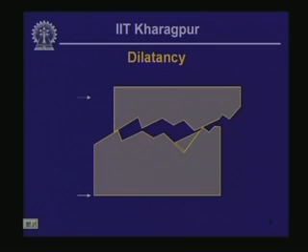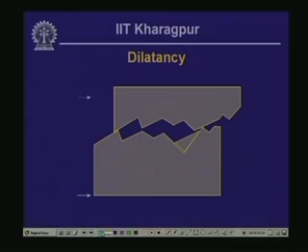You will see that in order for the sliding to take place, the top piece of the rock has to climb up in order to climb across the serrations of the joints, and if the normal stress applied during such a test is large enough, then in fact the joints may shear and break off, as is shown by this particular piece here.